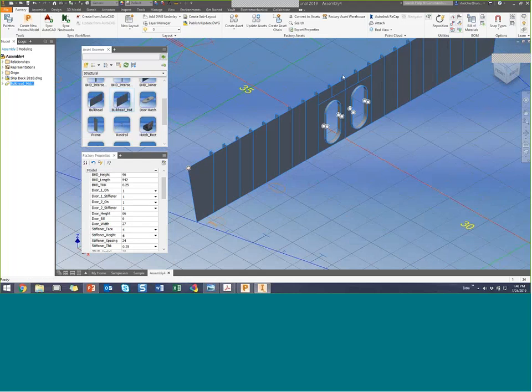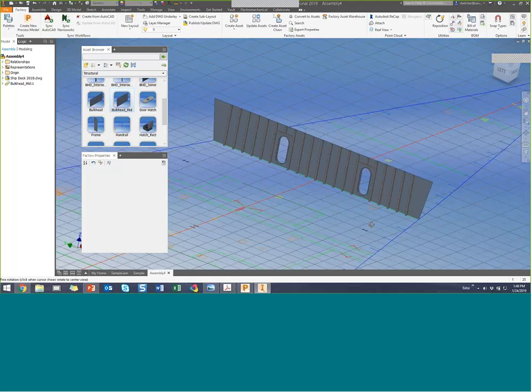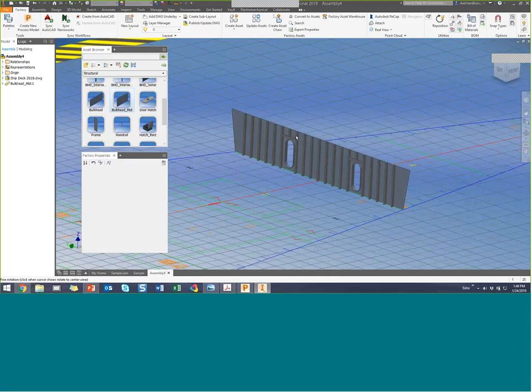The stiffener at the center line is 0, and then you count port or starboard, which one you want. So let's say, let's go to 4 one way, go to the 4th stiffener. The other one will go to the 5th stiffener. We'll click Update. So there is my structural model of a bulkhead for a ship design.